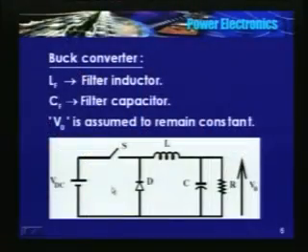See in this circuit, when S is closed, the source voltage is applied across D in the reverse fashion. So positive to the cathode, negative to the anode. So the diode is reverse biased.